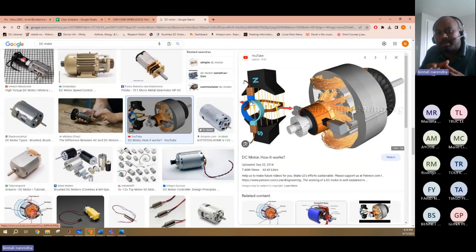Like the toy which you played with 5 years ago, when you try to move, it will move, but it will move very slowly, because the brushes and the commutator will wear off, and the amount of current which is flowing through the conductor will reduce, which in turn reduces the torque developed by the motor. So this is a major disadvantage when it comes to a DC motor.